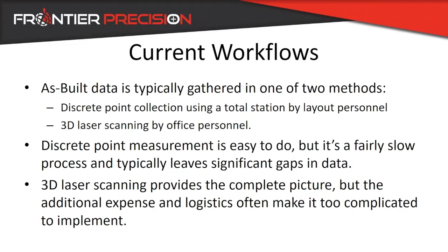and you have the layout personnel, and they're just clicking off measurements, sighting or actually just walking with the prism pole. Either way works, but you're doing a single discrete point at a time. The other option that people use is 3D laser scanning.